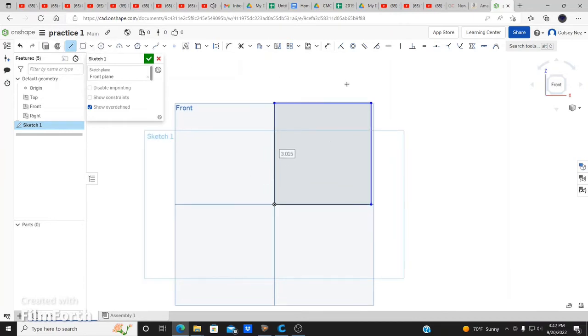That's it. Now I'm going to add my dimensions. I want to make everything else 3 inches too. How do you do that? There's this little icon that says dimension, with these two little arrows. Click onto that one, and it'll give you this dimension. What you're going to do is select the line only. That's it. Most people will do it the long way, going corner to corner. That's okay, but it takes a long time because it depends on how sensitive your mouse is. All you have to do is select the line that you want so that it highlights itself. Click that once, and that's it.